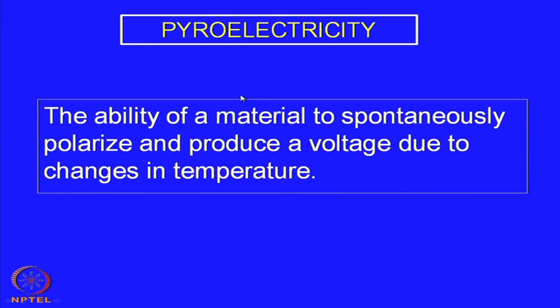They are basically insulating material or dielectric material, and there is a relationship between ferroelectricity, piezoelectricity and pyroelectricity. So, all piezoelectric and ferroelectric material are actually pyroelectric, but their pyroelectric coefficients may not be very large. In principle, they have a pyroelectric property, but the coefficients may not be very large, and therefore, all the materials are not used as a pyroelectric material.